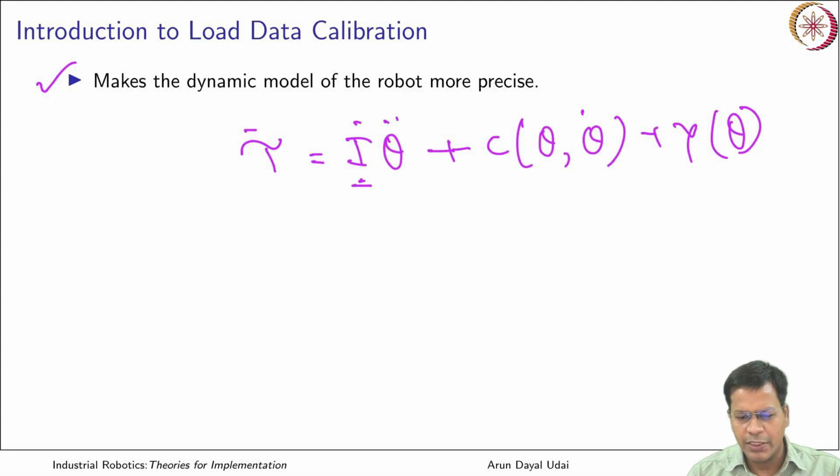You see the inertia term is there and it is a significant term. It carries a huge amount of value and contributes a lot to the torque at the joint. If the robot is moving at a good velocity, you will also see that velocity affects the torque. This is the contribution due to centripetal and Coriolis effects, which is again a function of mass also. The masses of the links go here and the velocity comes here. If velocity is significant, this term becomes quite significant.